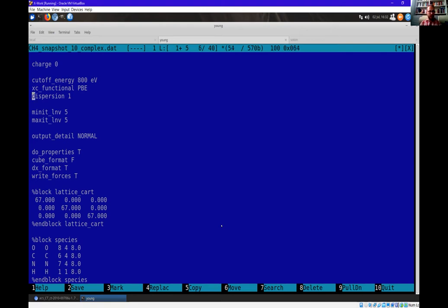I am turning on this empirical dispersion correction that Chris briefly mentioned when talking about the capabilities. So it's a correction for a deficiency in density functional theory, which makes biochemical systems behave better or give more accurate results. And then Chris mentioned the inner loop and the outer loop. So in the inner loop, Onetep optimizes the density kernel, and in the outer loop, it optimizes the localized orbitals, these so-called NGWFs. It has some good logic for determining how many inner loop iterations it should do, but you can override it.